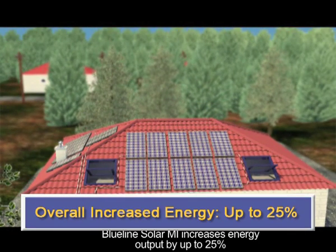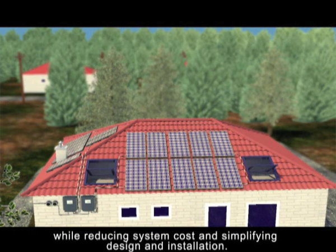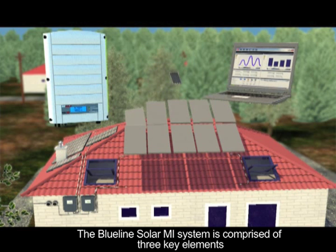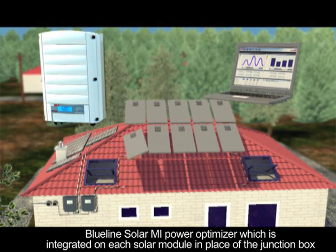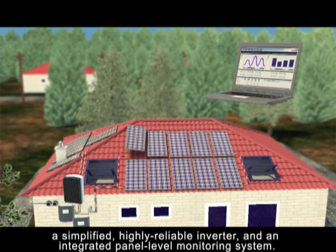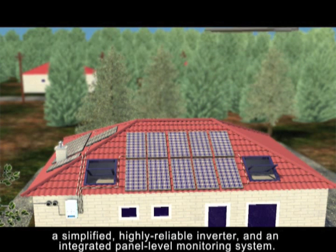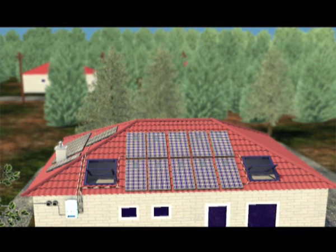Blueline Solar MI increases energy output by up to 25% while reducing system cost and simplifying design and installation. The Blueline MI solar system is comprised of 3 key elements: the Blueline Power Box, which is integrated on each solar module in place of the junction box; a simplified, highly reliable inverter; and an integrated panel-level monitoring system. The Blueline Power Box optimizes power harvesting by performing MPP tracking of each panel individually, while keeping the string voltage fixed.